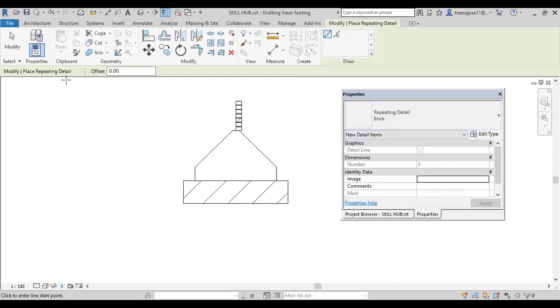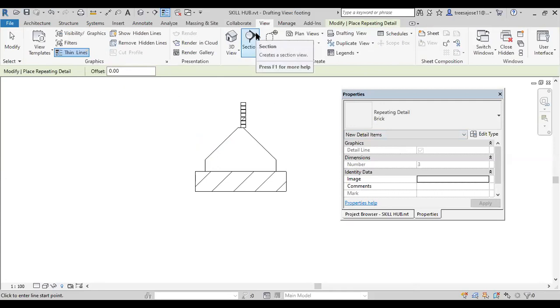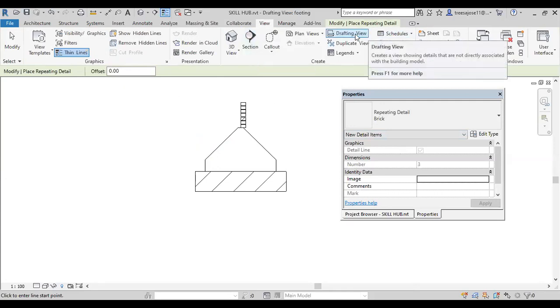Multiple drafting views we can also create. A drafting view for septic tank details and a drafting view for rainwater percolation details, so that we can easily drag them into the sheet. For that, you create one more drafting view. Actually, I don't have the septic tank details or a CAD drawing, I will just show you where you have to go. For that, I need a new drafting view. That time you again go to drafting view.